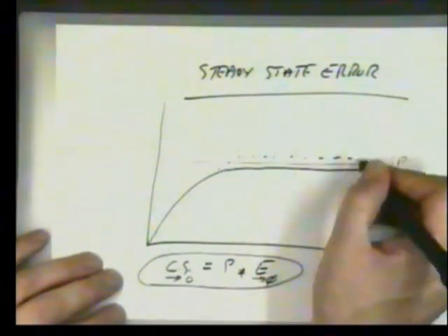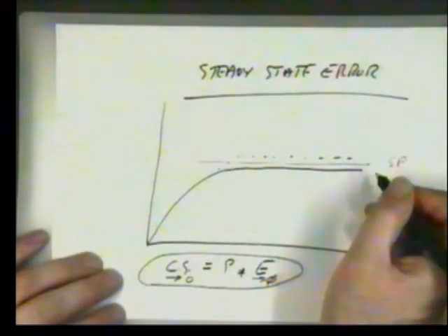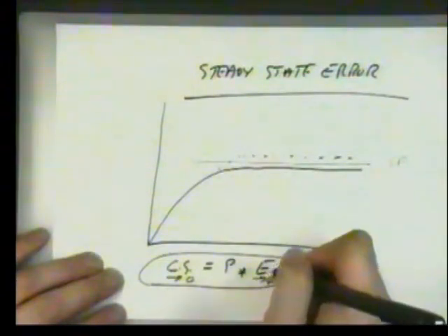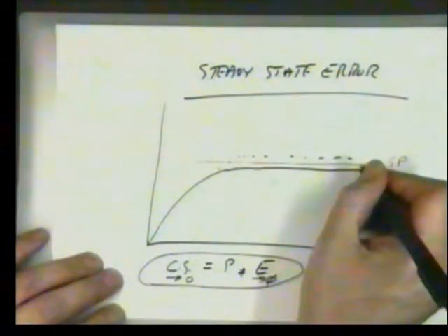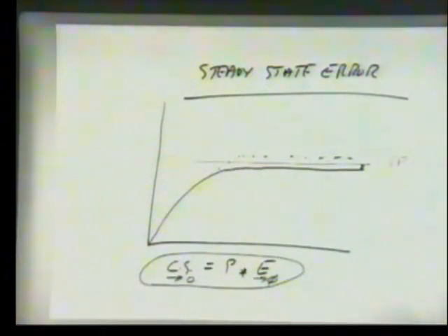In fact, we've reached the point where we've reached a very stable state and we are hardly applying any control output whatsoever. In fact, that control output is just about enough to balance the natural loss to energy in the system. We never quite make it. So we can't use a proportional structure because the error is tending to zero.